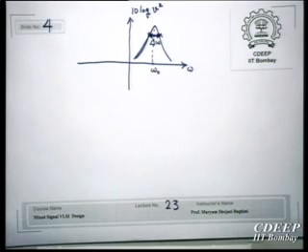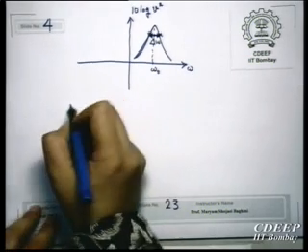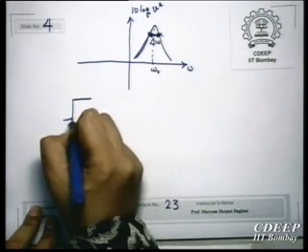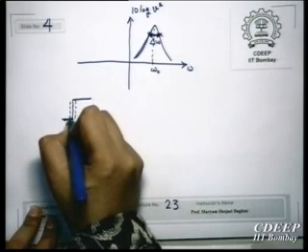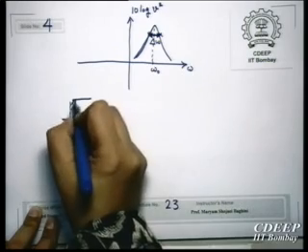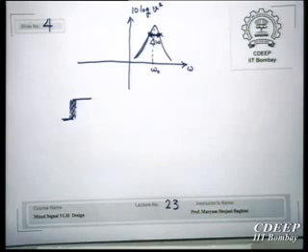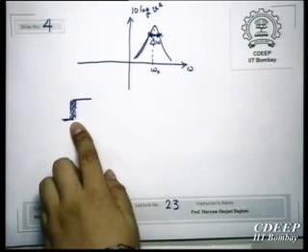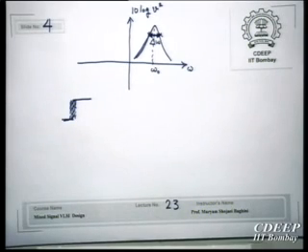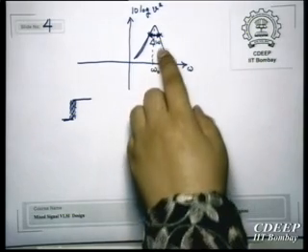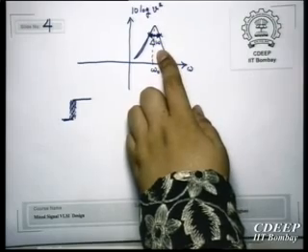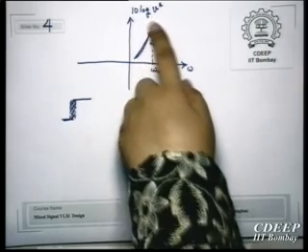Effectively it's not a sharp edge. Even if you look at it on a scope, you will see something blurry here. A scope is not even able to trigger properly because this changes randomly. Therefore, the scope will show you this type of ribbon here. So this strip is actually jitter. The edge changes, which means that effectively the phase, or actually the frequency, is changing. This appears on the spectrum analyzer like this.